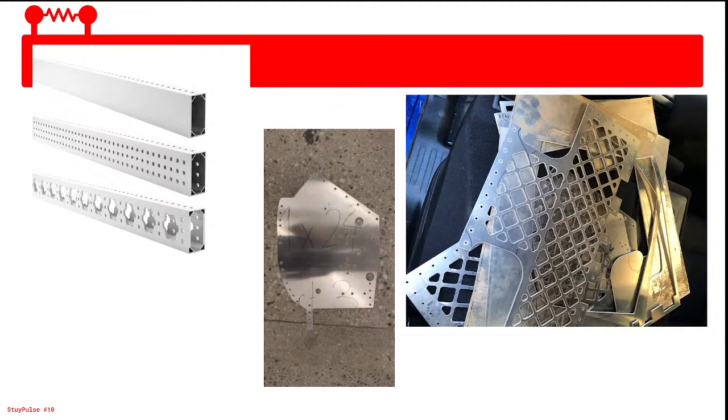So it is really important to understand that yes, your material selection is important, but equally important is how you use that material. Something we learned after doing this is that we want to reinforce all the areas around bearing blocks and high load, high stress areas, and make sure those are as protected as possible so that they have less load and they aren't as likely to break or crack.